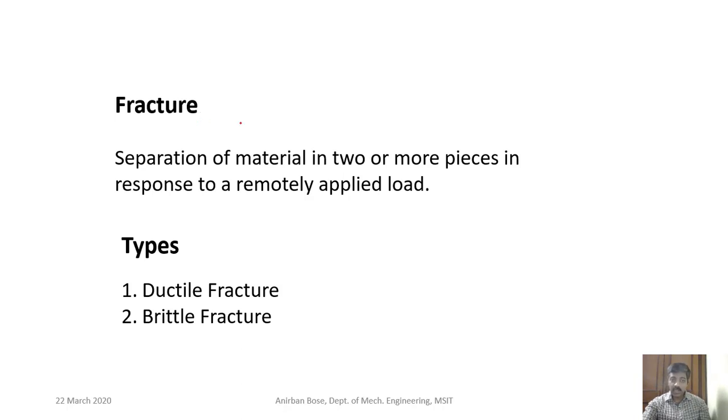But in case of cutting, the material is separating at the point where the load is applied. On the other hand, in case of a fracture, it is a remotely applied load, so the load is applied in one place but the material is separating maybe away from that point. So this is the definition of fracture.